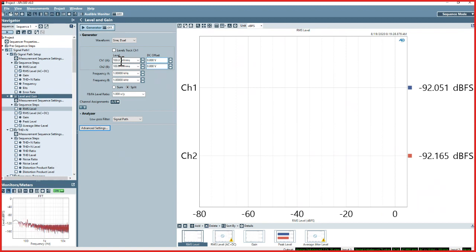Usually you have a discontinuity in termination on the serial interface cables. So it may be worth calculating out and actually adding a resistor so that you have matched impedances on the cable. That would probably be the next most successful place.